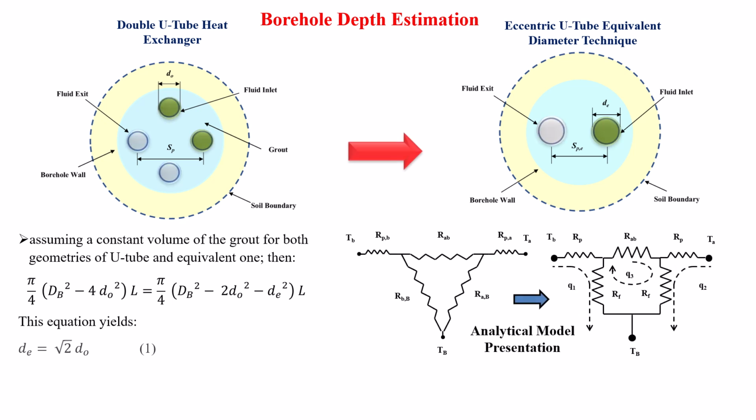And generally, as in previous episodes, we have used the similarity and analogy between the thermal resistances and the electrical circuit resistances as shown in this figure, and we have derived the borehole thermal resistance.